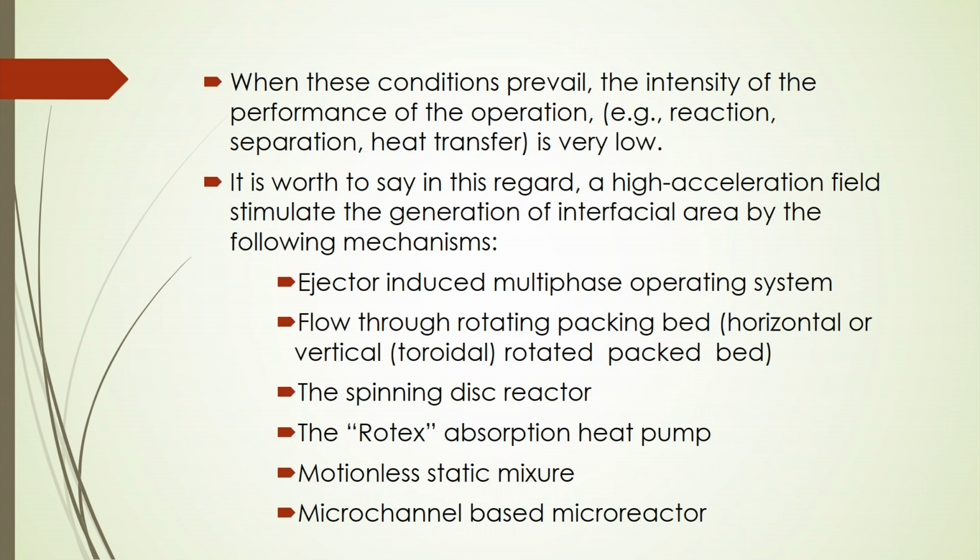So, there is the formation of bubbles, which will give you the interfacial area. Whenever the bubbles move downward, at the same time the buoyancy force will try to move them up, and there will be a certain condition at which this upward buoyancy force and the downward liquid momentum may balance, and the bubbles may reside for a longer time in the column or in the system or in the unit.